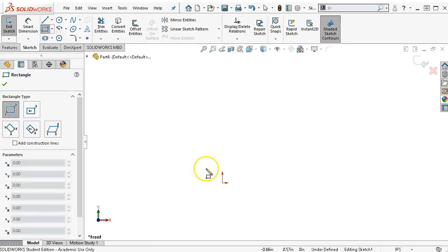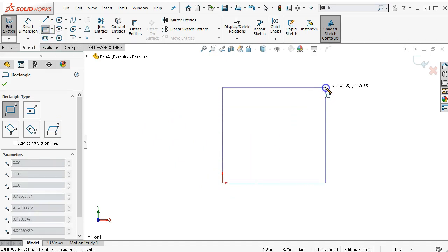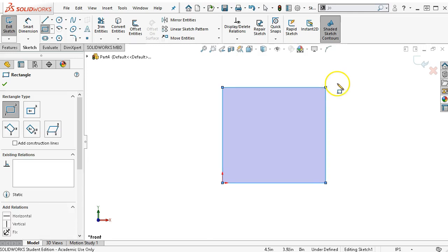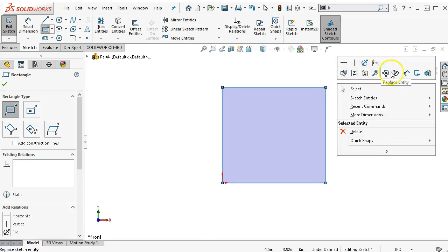So our outside dimensions from the origin, find the coincident, and then I'm just dragging out some distance. Right click, and we come over to Smart Dimension, which is the same as coming up here. Watch out for the sketch numeric input. If you like to enter the values as you're adding the dimensions, that's one way to go.